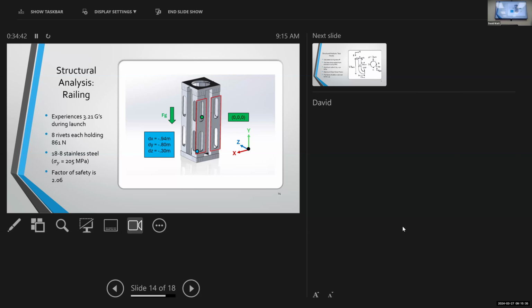For aerospace, and really for anything, factor of safety should be set out ahead of time, right? It's a requirement you have to meet, and I'll talk about what your specific requirement is and should be in a minute. But your factor of safety is defined for you, and if it's not defined for you, go figure out what it should be and what you're going to work to, right? And then it's 1.5 for you guys maybe. And then you say, okay, the allowable load that my structure can carry is say 1,000 pounds, right?